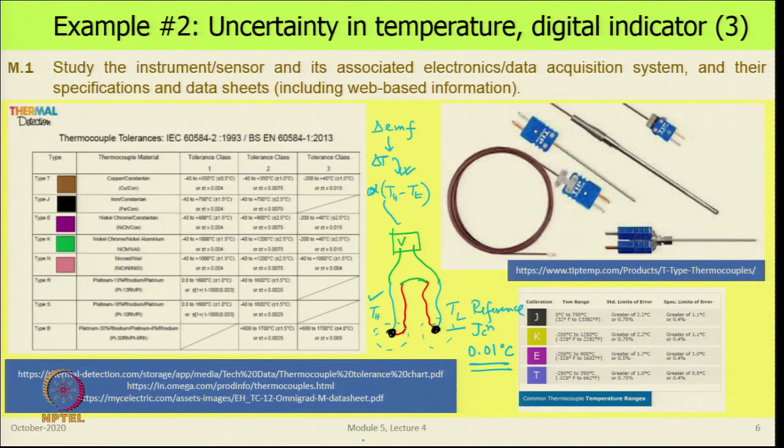So, that is how the thermocouple works, but the signals are very low, and so what we do is send it to an amplifier and then digitize it and then do this reverse calculation, convert the EMF into a delta T, we need a calibration there, and then add the reference junction temperature to it and we get the temperature that we are trying to measure. So, when we are measuring, it is this part here which we will take and locate it where we want to make the measurement.